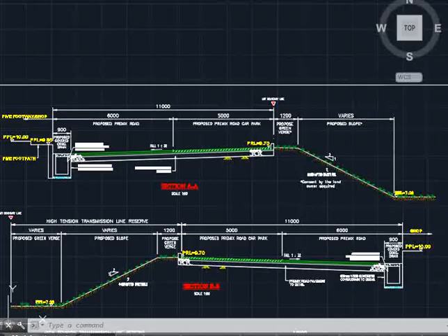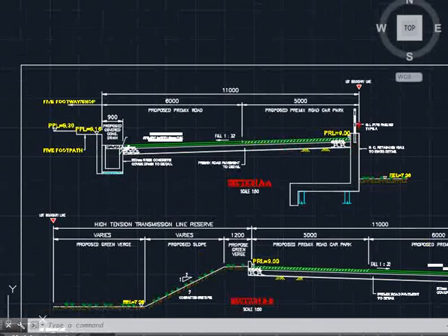Let's say now you are unable to get the consent from the landowner. Now this slope design cannot be applied. For that, you will have to work out a retaining wall without trespassing into the adjacent lot and impose no changes to the existing conditions of the adjacent lot. Now, when there are differences in terms of the elevations, as a safety precaution, the safety rail shall be required.